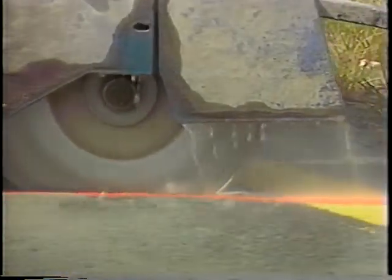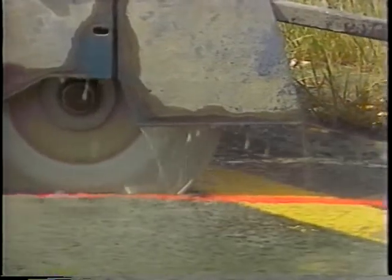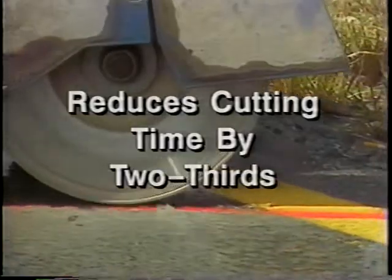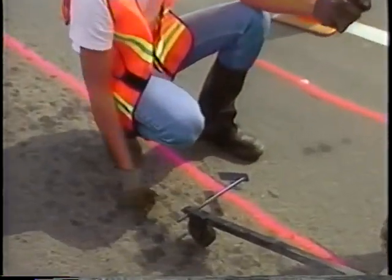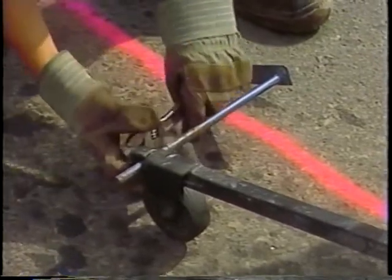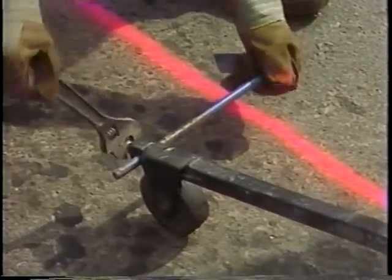Studies have shown that using a diamond blade, a high-horsepower saw, and water cooling reduces cutting time by 2/3 compared to the less expensive dry-cutting system. The slight increase in initial saw costs can be reclaimed in savings of time, labor, and equipment longevity. Regardless of the type of saw used, it should be equipped with a depth gauge and a horizontal guide to assure proper depth and alignment.